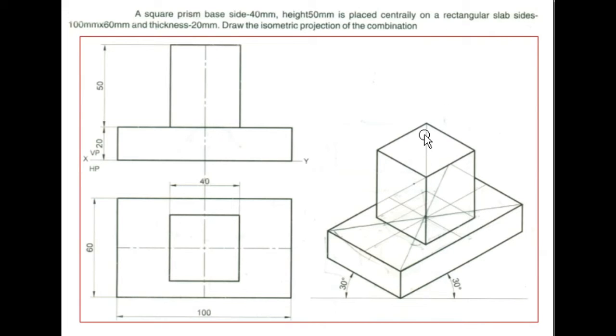What happens is that line will be hidden, so don't represent it by a visible line. Represent all the other lines with visible lines, and whichever lines are cut when the prism is placed, the lines on the rectangular face in this particular region will be hidden. So trim those lines or mark them with hidden lines. Can you see here, these lines have been marked with a thin line representing that they are hidden, right? So this is how the problem has to be solved.